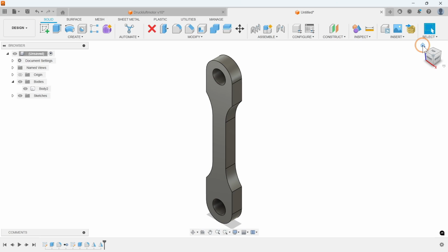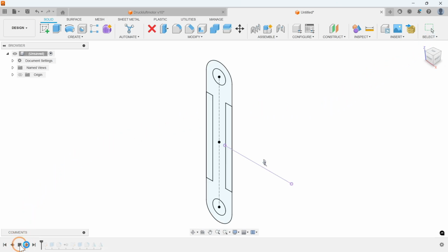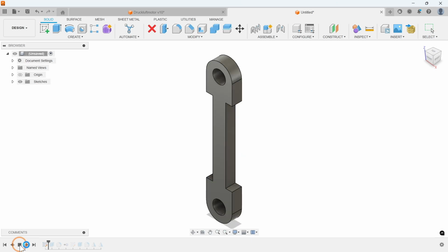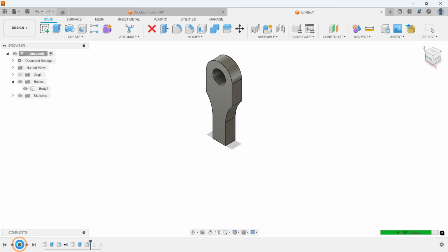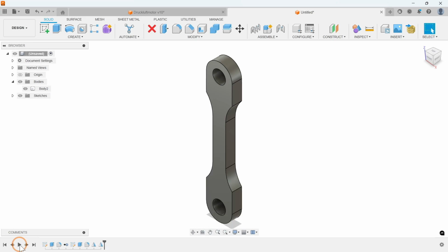Thus, we are finished. In this video, we have constructed the connecting rod of our air motor in two different ways and got to know some helpful functions. On the first path, you use the slot tool to shorten the drawing of the contour. On the second path, you learned a bit more. You can now draw circular arcs both quickly using the line tool and precisely with the arc tool. You can also efficiently create symmetrical contours through mirroring. Finally, you learn to adjust the order of elements in the construction process to make changes and optimizations flexibly.